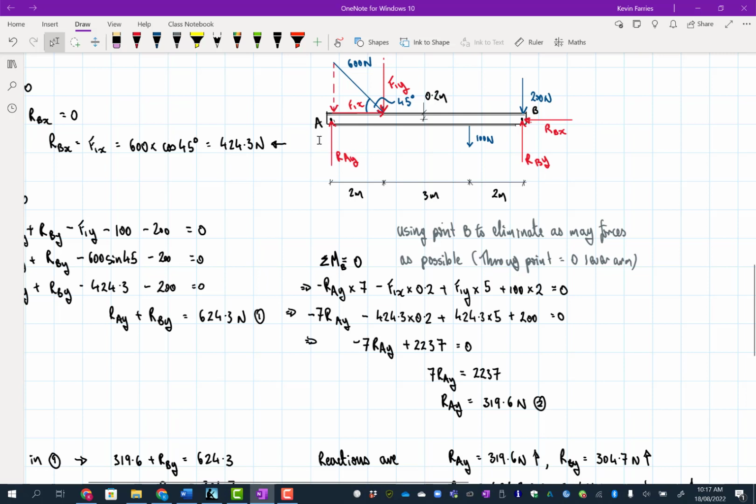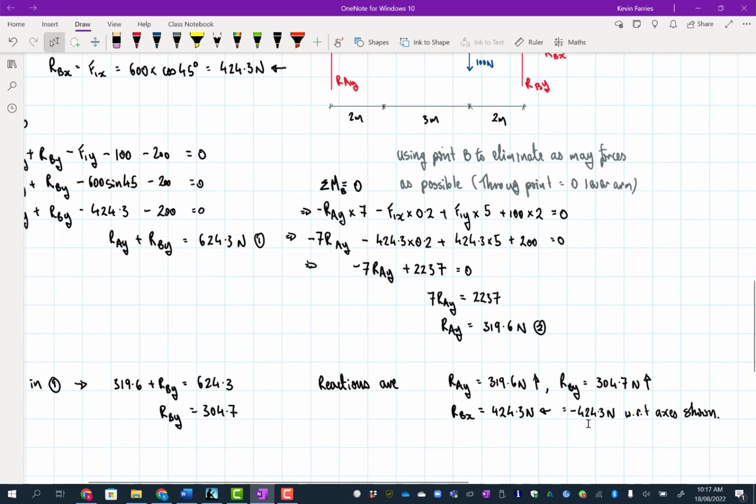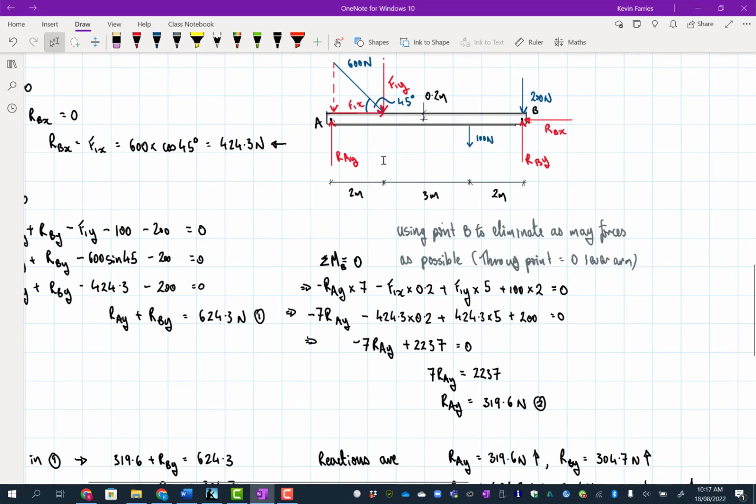Okay, so it's a little confusing. You can think of these as the whole vector in that direction, in which case you use your positives and negatives to show the direction, or you can think of these as just being the magnitude. Now that's what I'm doing in this case. I'm thinking of these as the magnitude. They're all positive, and then I'm using the arrow to show the direction. And therefore, if I've got that direction right, I use that direction to decide whether my moment's positive or negative. All of these magnitudes should come out positive. If they're negative, then I'll go back and check, could that be the other way around? In this case, it can't be. I know that those are the right directions for these just by looking at it.